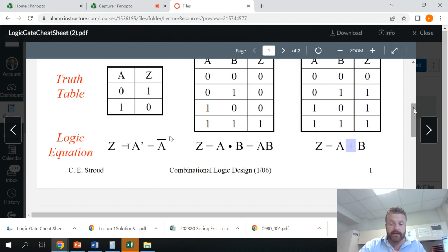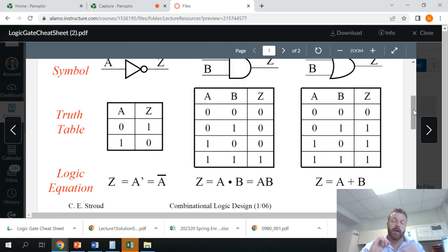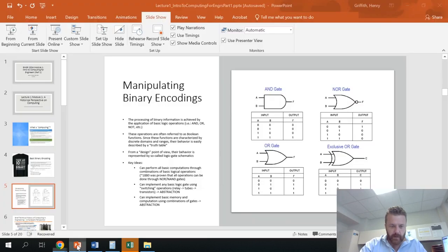And in addition, since these are functions here, they are Boolean functions, we need to know the relationship between the output and the input. And since these inputs are Boolean variables, they can only take on a 0 or 1, the total possible combinations of inputs is pretty small. So rather than, if you think about traditional functions where you might have to draw a graph in order to show the relationship between all the possible inputs and all the possible outputs, in actual digital or Boolean analysis, we can list all the possibilities in a table. And these are what are known as truth tables.